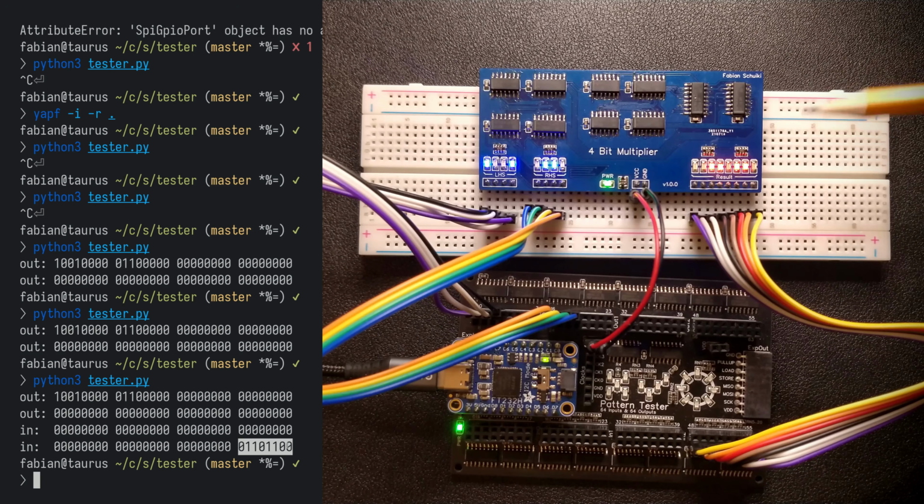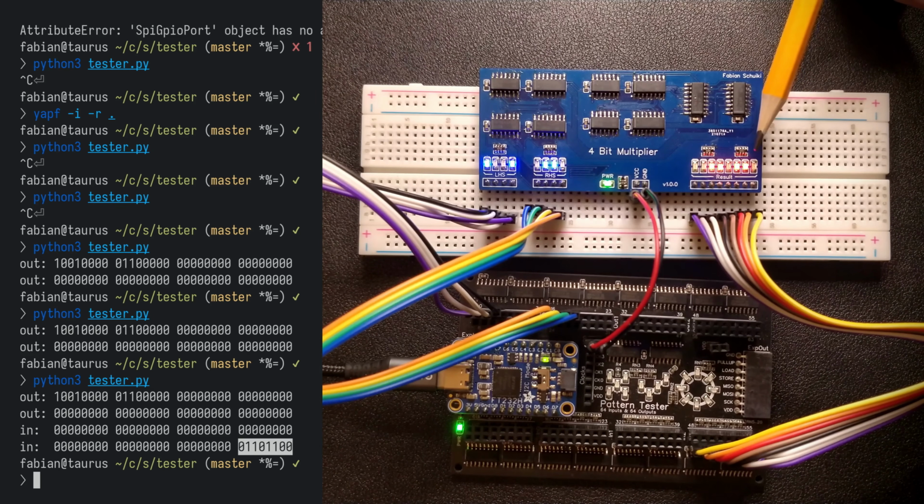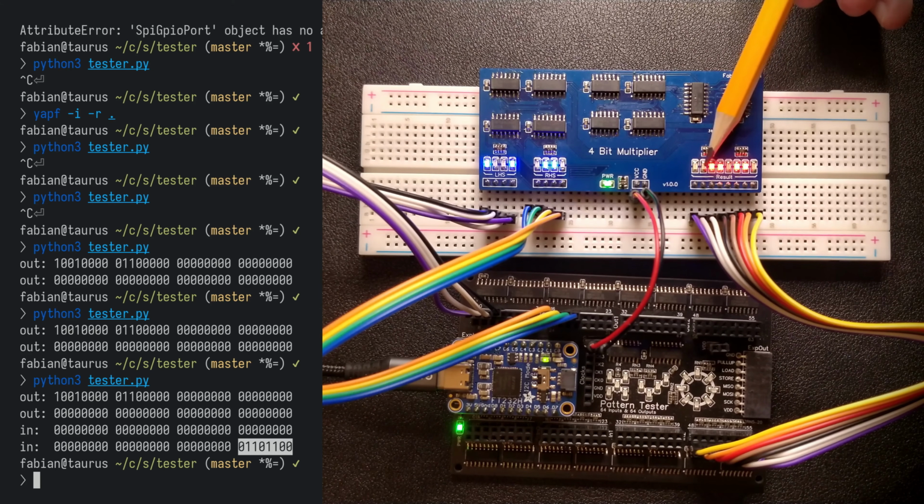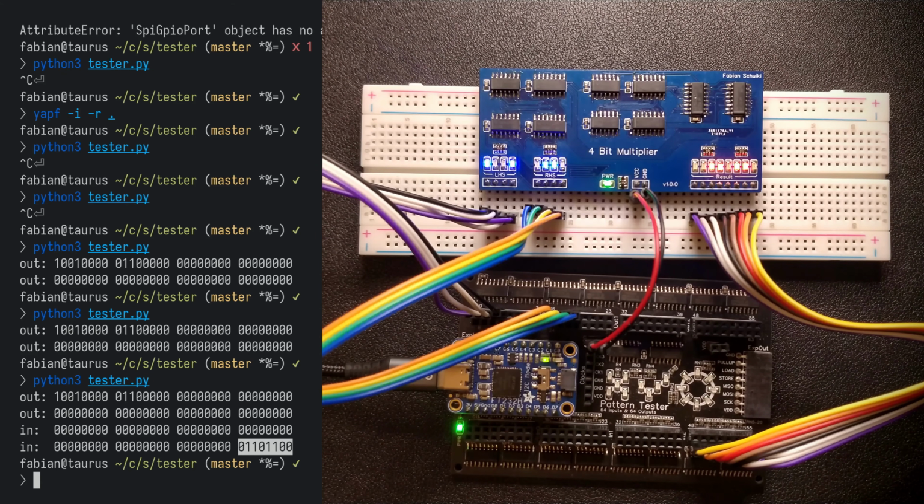Keep in mind that the multiplier produces the least significant bit on the right and the most significant bit on the left, as you would read it on a piece of paper. But we've connected the least significant bit to bit 0 of the input, so it's the leftmost bit here. So this appears reversed in how we look at it in this printout, because we are trying to match how the bit arrangement is on the tester visually. And so you can see that the least significant bit is 0 here, and then we have 2 1s, a 0, another 2 1s, and then 2 zeros. And this is exactly the pattern we are reading back.